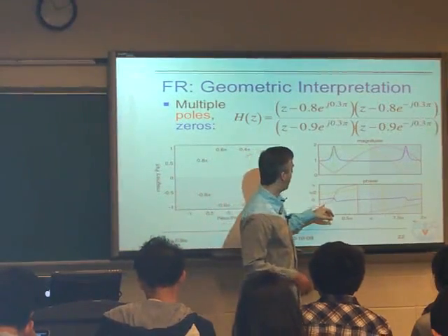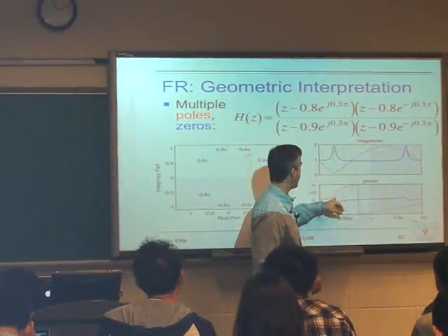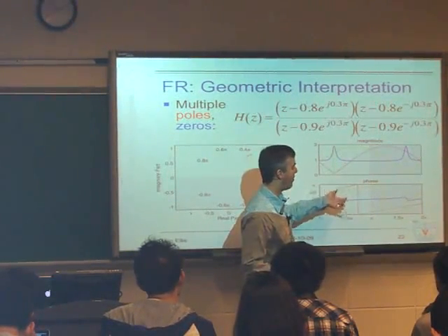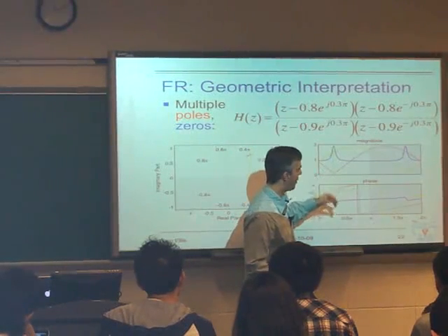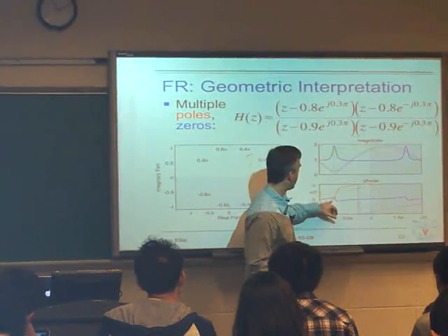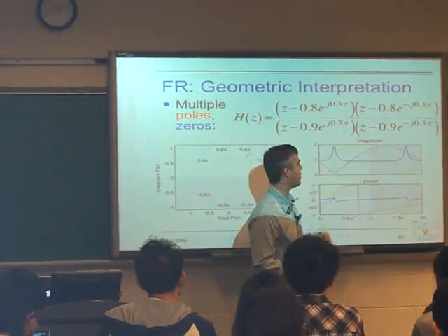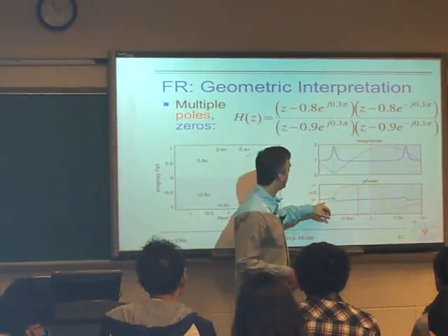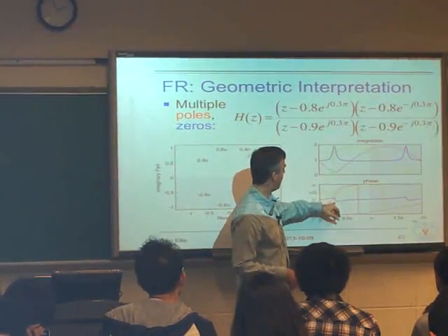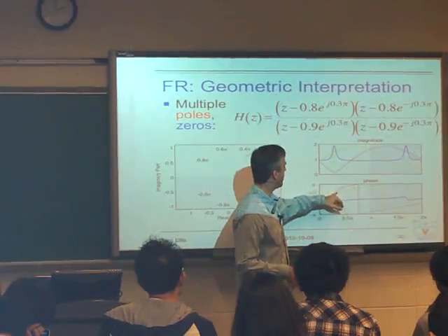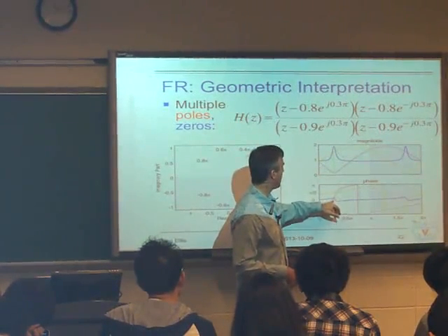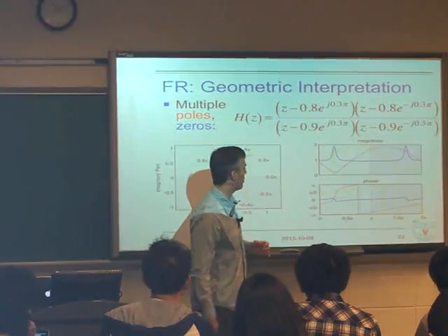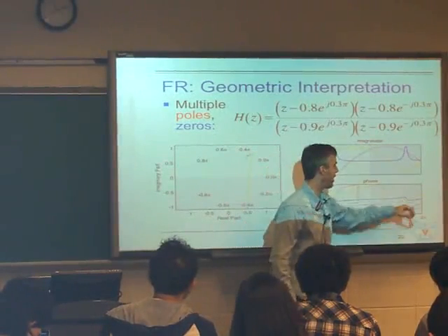Similarly, for the phase response, we can plot the actual overall phase response, because I've drawn the poles as if they were zeros. So it's the difference of the red and the blue curves plus the difference of the orange and the green curves. And so we get this thing where the phase response is close to 0 the whole time. But there is this kink around here because even though they're close to 0, they're close to each other. They have the largest difference around this critical point here when they get close to the root. And so we see the overall phase response.